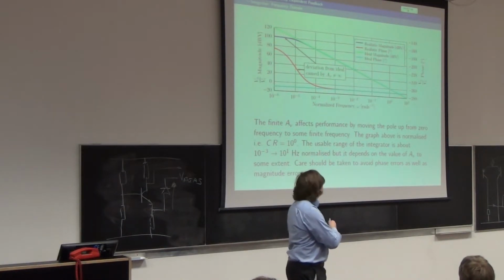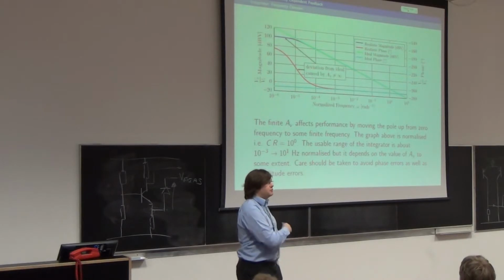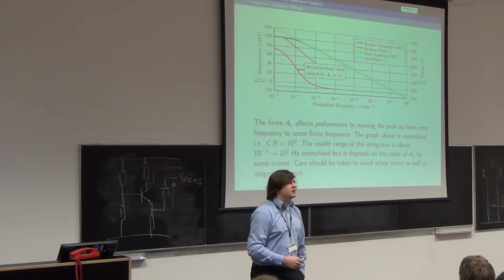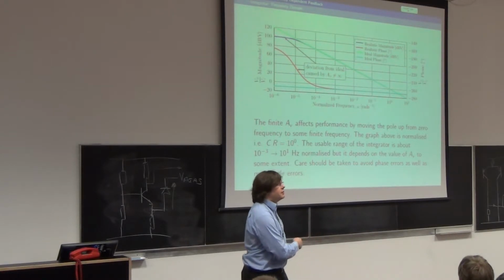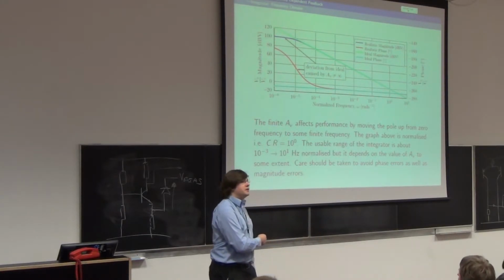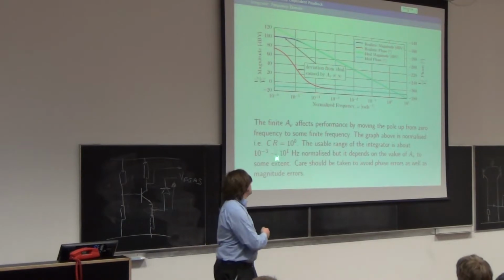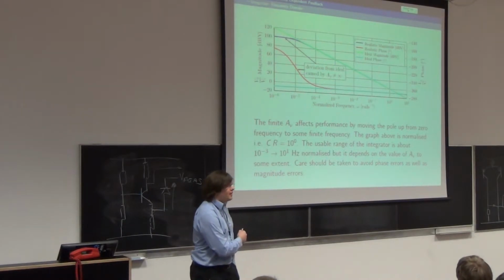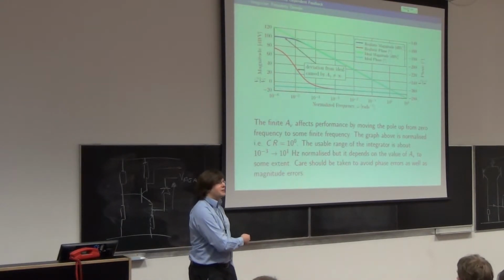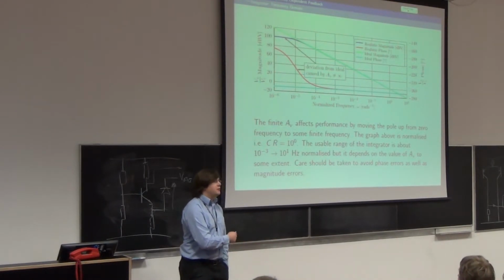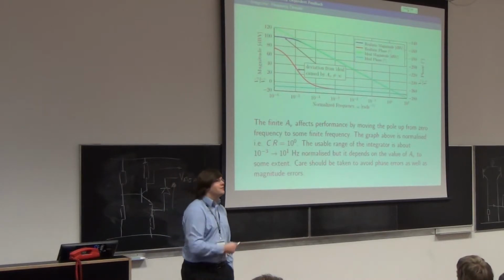Well, you can, if you want to, download the simulation and run it, and you'll get an axis in hertz, and I think I chose that as a kilohertz, just to give you some idea. But if you wanted to do it at a different frequency, there's no reason why you couldn't. You just change the time constant. Of course, if you go beyond the bandwidth of the op-amp, bad things will happen. It won't look like an integrator anymore. So you can't go forever.